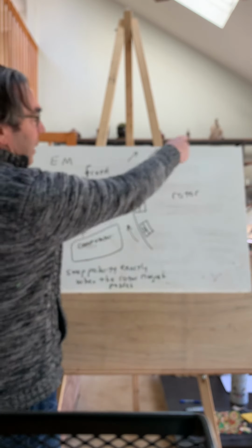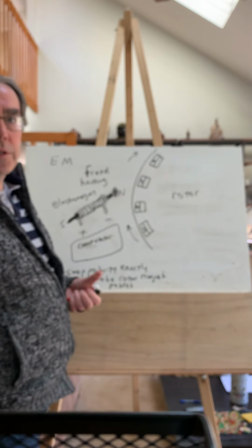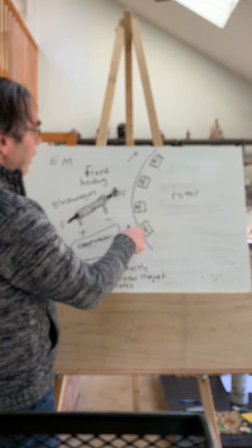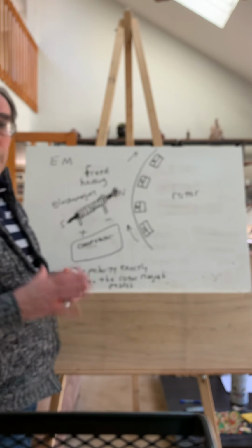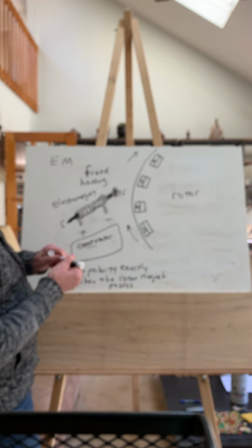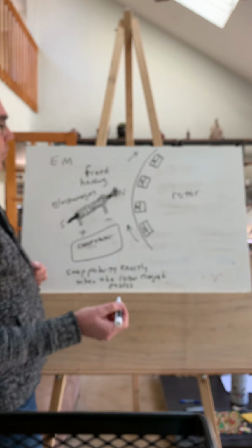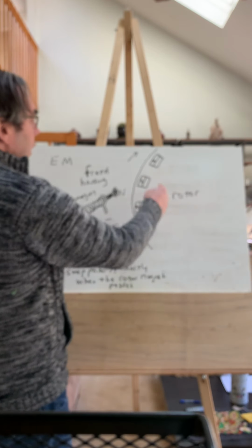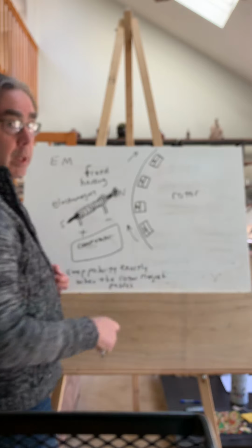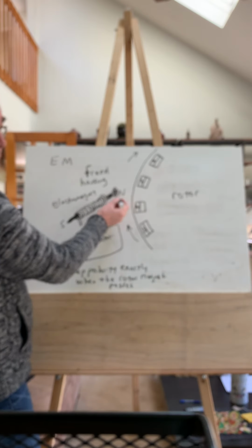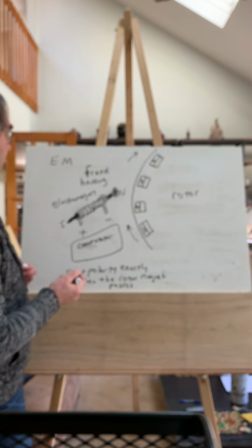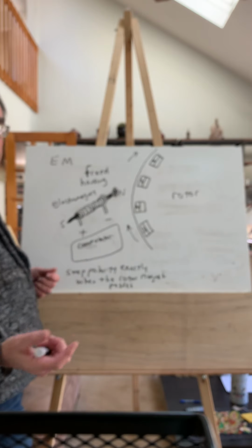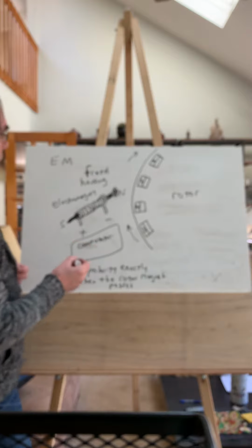And if we have 12 magnets on here and it's rotating at 10 revolutions per second, that means it's going to have to do that 120 times a second. But we can do that. We can get that kind of precision. So, the basic features of a motor, the basic minimum necessity: you need a rotating element, you need permanent magnets with alternating polarities, and you need an electromagnet that can swap the polarities. Now, we could do that by taking a battery and going like that back and forth, right? But, you know, we have alternating current to do that.